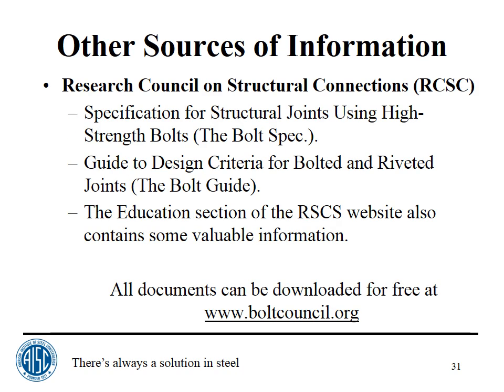So continuing on, that's the AISC specification and manual. And then other sources of information, the Research Council on Structural Connections, RCSC. This is the specification. These people put out the specification for structural joints using high-strength bolts. This is the bolt spec listed there in parentheses.